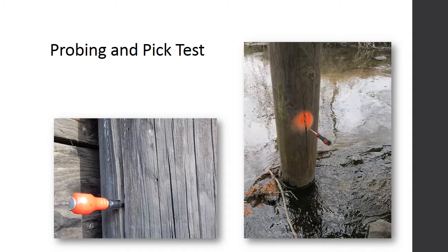A pick test on non-decayed wood will give an audible sound that one would expect to hear when wood breaks. A pick test on decayed wood will result in a brash or brittle failure across the grain with few, if any, splinters, and the sound will not be as loud. The pick test can subjectively differentiate between sound and decayed wood in weathered specimens that might otherwise be mistaken as decayed under comparable conditions. This simple test does require some experience to reliably interpret the results.